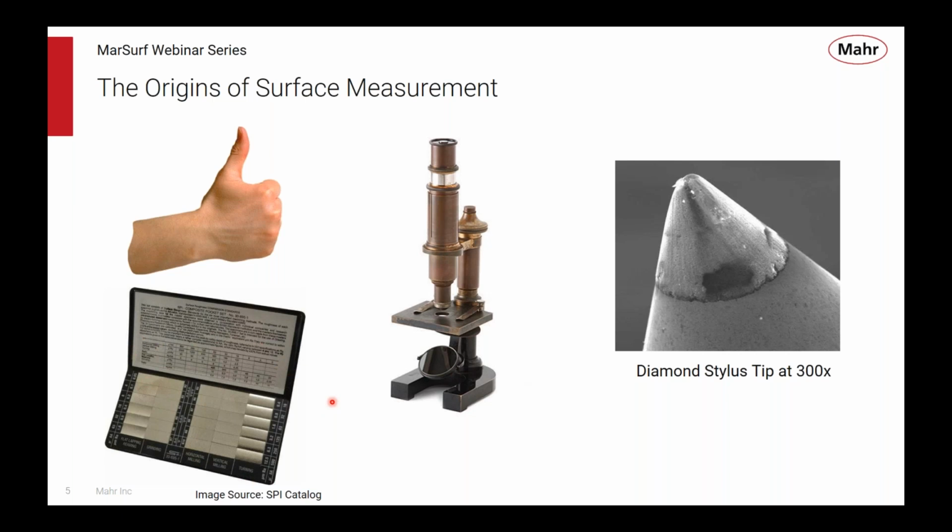And he would have taken his thumbnail and scratched a sample and then scratched the part, and then scratch another sample and scratch the part he was machining, and then scratch the next, and try to find the one that is the most similar to the surface he actually is trying to measure. And you see in this box of masters, there's grinding, milling, turning, types of surfaces with different types of surface finish, and that's still in use some places today.